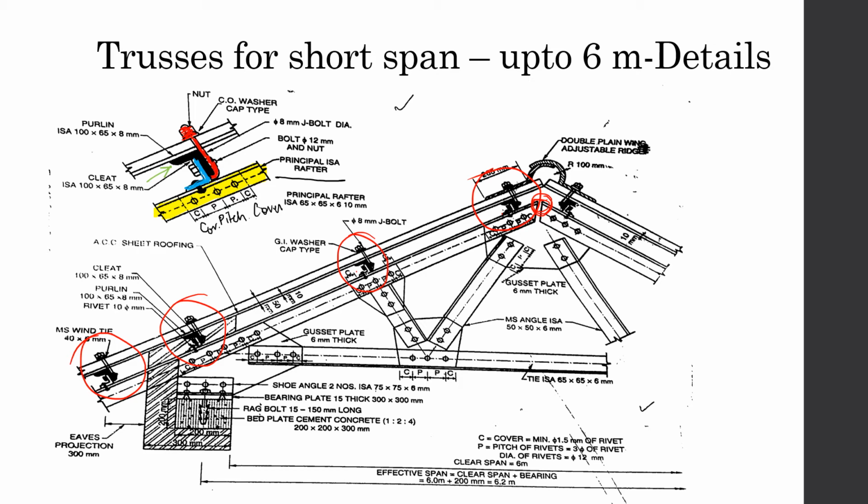But here you can see it in a section, but a purlin moves from one end of the truss till the end of the truss. It is not a small member, it runs through and through the length of the truss. So this is a through and through member. So a purlin moves through and through, and a cleat is only where the support is needed.